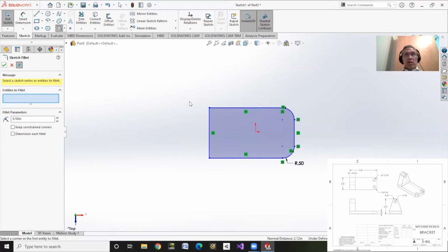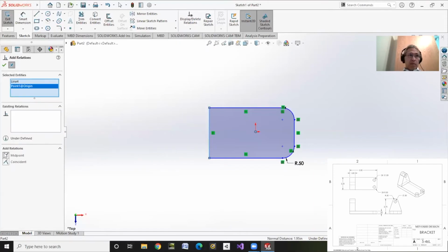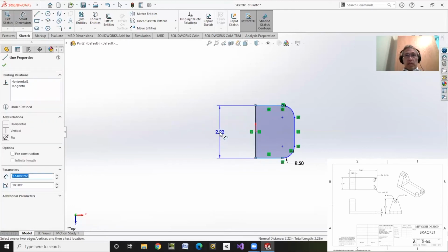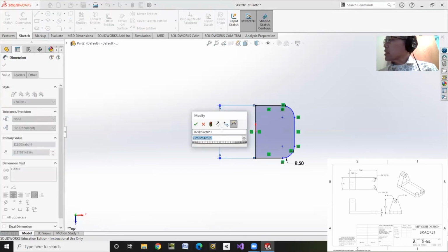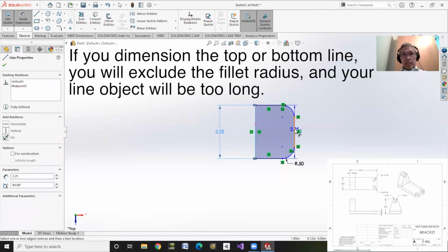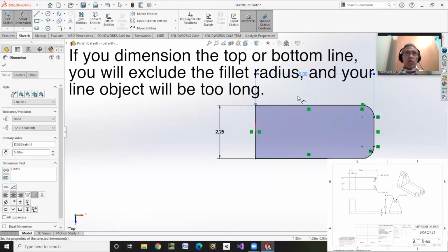Okay? Now, normally I've been having you draw corner to corner, then making that the midpoint. But this time instead, I'm going to make this edge and the origin the midpoint. Okay, and notice it kind of got weird there, but that's okay. The dimensions are off, but that's all right because we can just do our smart dimensions. So we'll smart dimension this, and I could have dimensioned that left edge instead. Let's see what that is. The width is 2 1/4, so 2.25. And then I know the length from this edge to this edge is a total of 5. Okay, so that is the bottom.